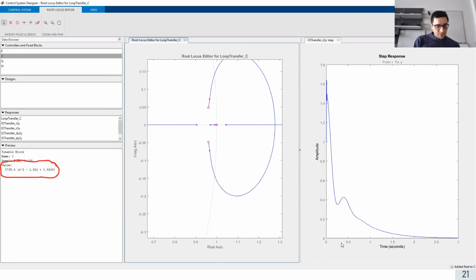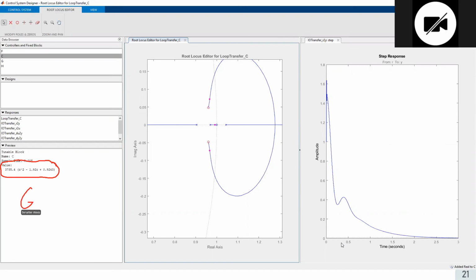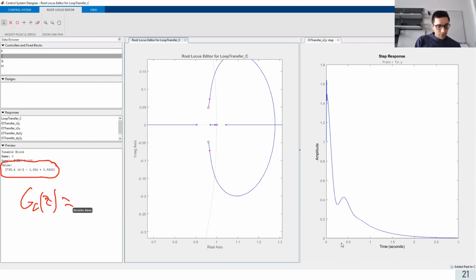This controller here is just C(z) equal to a numerator, here z squared plus something z plus something, whatever, divided by 1. And so this is not a causal controller. I'm just having a controller which consists of 2 zeros and no poles. So this is not causal, so this is not realizable. The plant is perfectly fine because I've got 3 zeros and 3 poles, or even 4 zeros and 4 poles. And so the plant is still causal, but the controller is not.